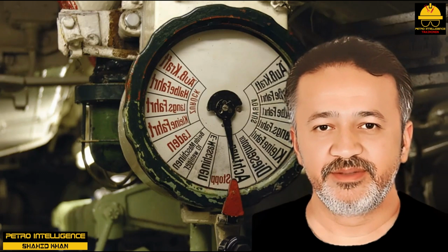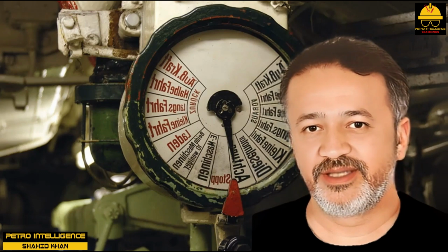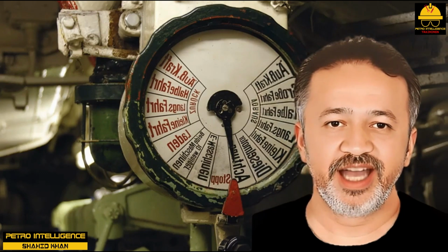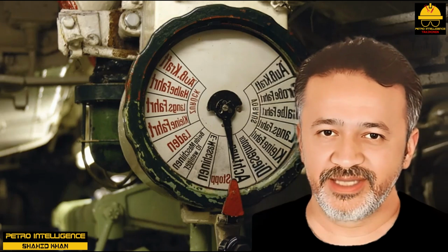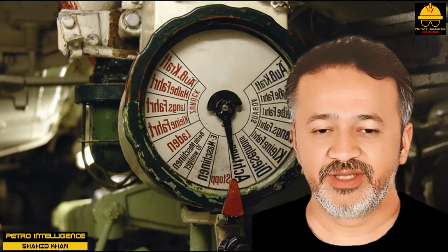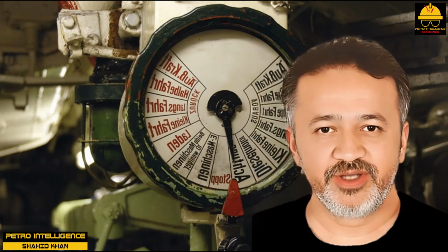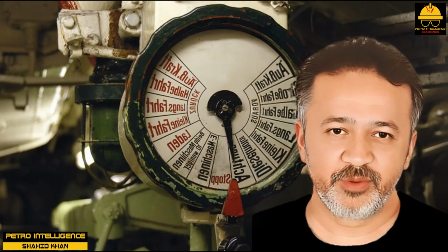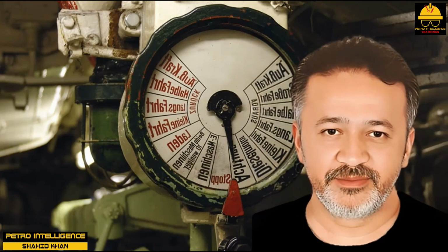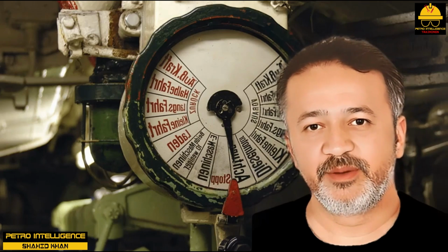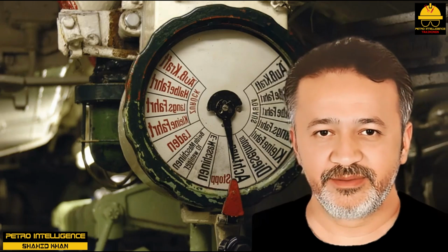a level indication. A bubbler system is a level measurement device that forces air through a tube that is positioned in the liquid. The liquid's resistance to flow registers on a pressure-sensitive level gauge that converts the pressure to a level indication. Bubbler systems are used to measure levels in open vessels.